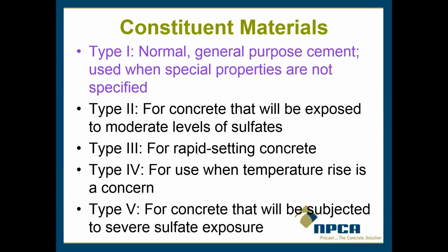And type 5 is used for severe sulfate exposure. So if you're doing something that will be exposed to seawater or something like that, where it's constantly having chloride attack it, this will help out with that.